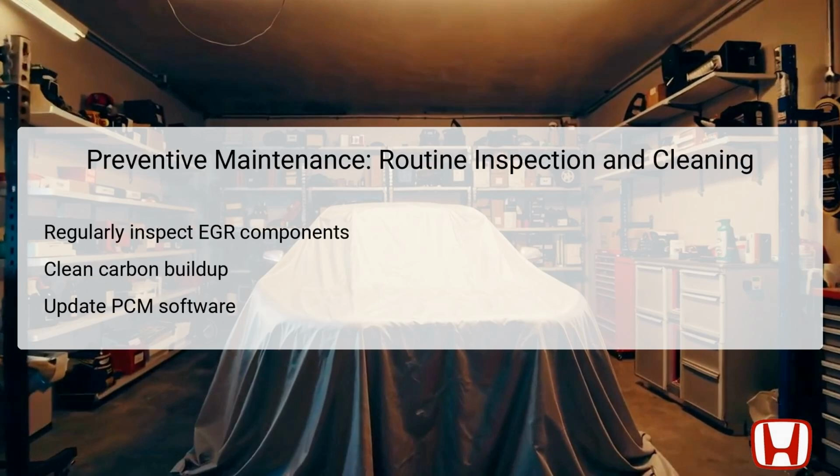Prevention starts with routine inspection and maintenance of the EGR system. Regularly checking the EGR valve and associated passages can prevent carbon buildup that leads to blockages and faulty readings. Cleaning these parts with throttle plate cleaner maintains unobstructed flow and sensor accuracy.